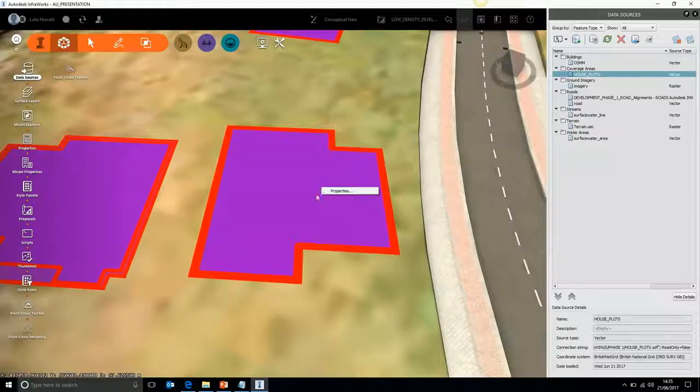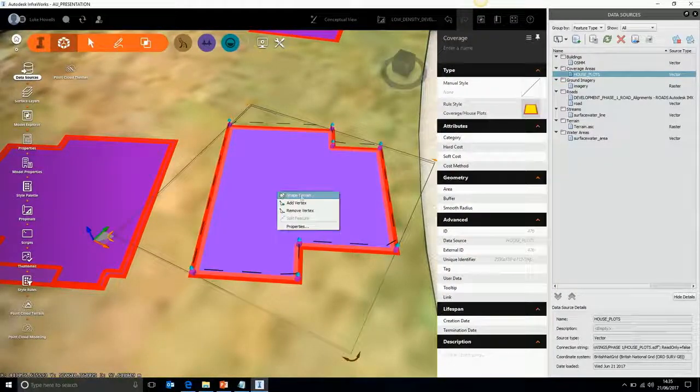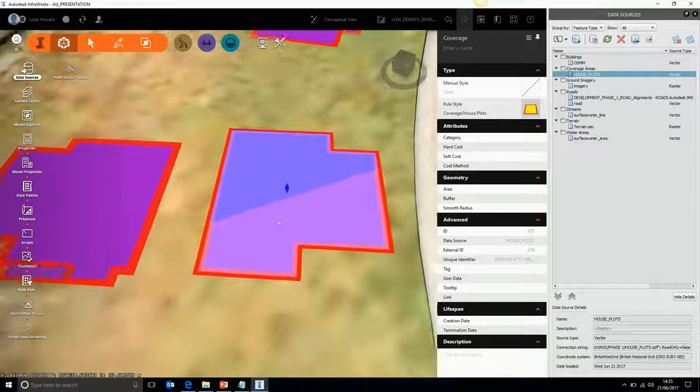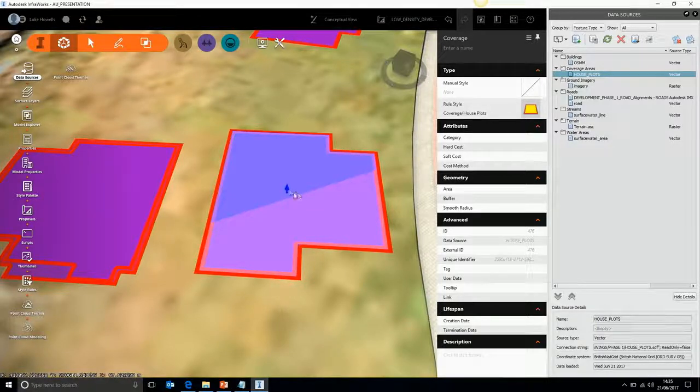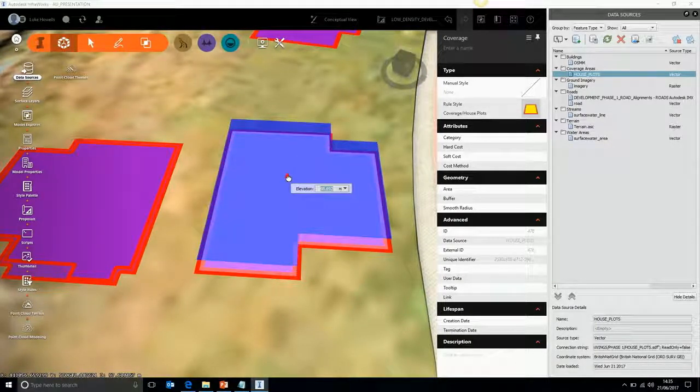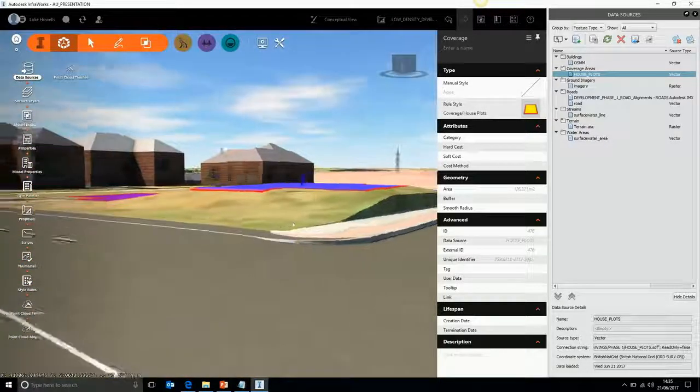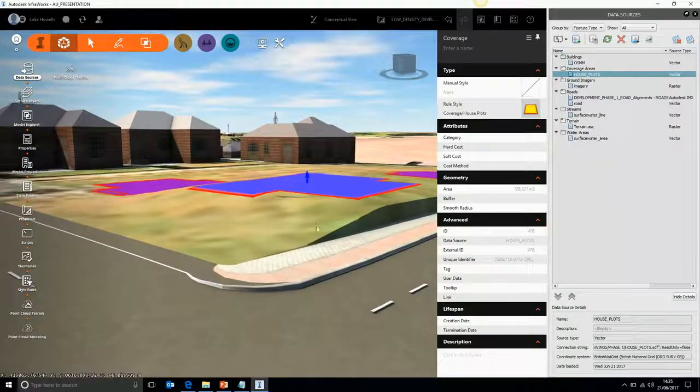These ones we've got in though, we can just come in, select it, and we can actually do the right-hand click and shape it. So you can see on this one at the moment, I'm half in cut, half in fill. It's just a case of pulling it up. I can manually insert a level, or I can actually come round and type it in where I'd like it to be. And it will blend all the surfaces for me as well.